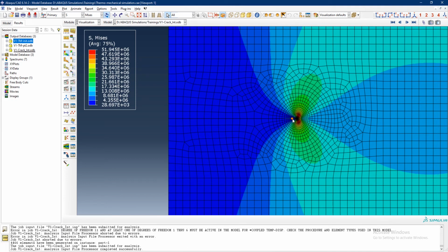Normally the cracks initiate and propagate under tensile load. Under compressive load they generally do initiate and propagate in ceramics, but usually that is not the case in metals. But in the thermomechanical fatigue case, because there is heating and cooling, there is a compression cycle, and after that there is a tension cycle, and in each compression cycle basically the crack closes up, and in the tension cycle it opens up again to absorb energy, and that is a complicated problem. So therefore we need to define the crack face interface, so this kind of problem does not happen when we define that simulation which we are targeting in the future. You already see the problem.